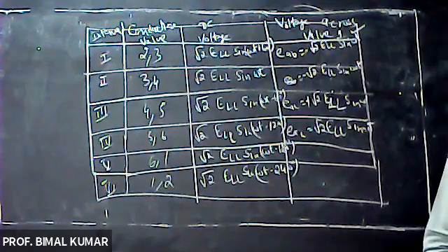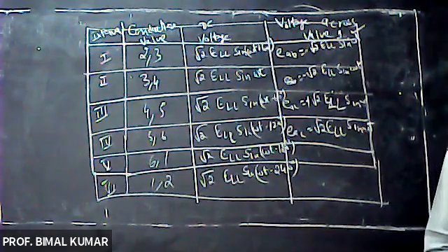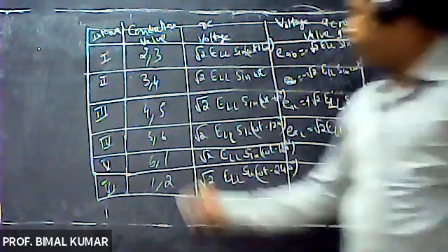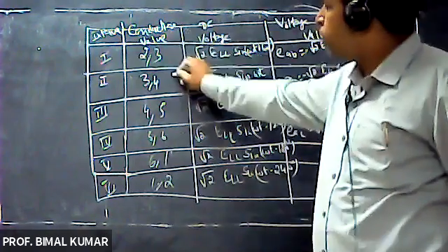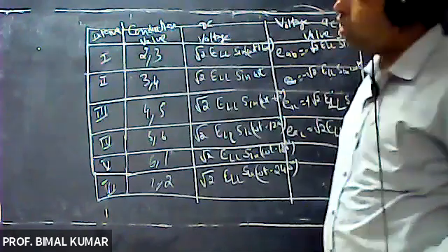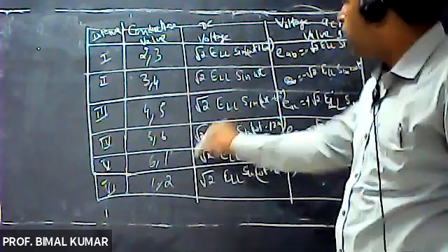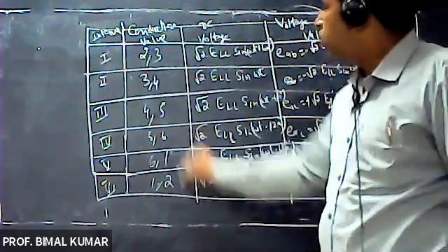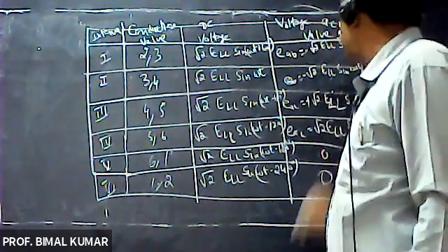During the last two intervals, that means from 241 to 360 degrees, what will happen? Thyristor valve 1 will conduct. During all that upper section, no thyristor valve 1 will conduct, all other four will be conducting, right? During interval 5 and interval 6, thyristor valve 1 will be conducting, so the voltage across it will be 0.